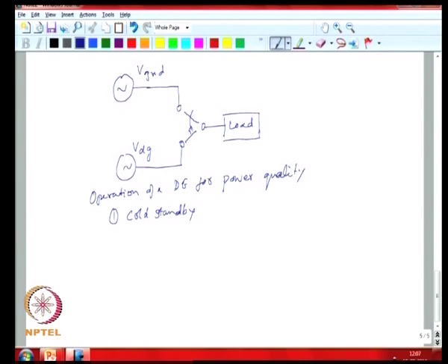And if you look at the startup time of a genset, it can take 20 seconds for a really fast startup genset to minutes for something which might need a little bit more warm up time to actually start up and stabilize to a normal operating condition.